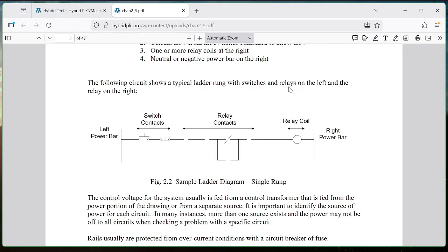Okay, same thing. What is a coil? An inductor, okay? V equals L di over dt. When you open or close these contacts, they don't immediately shut down the current, right? So as you open and close the contacts, what happens? The current's got to go someplace. It cannot immediately go to zero, all right? Everybody?